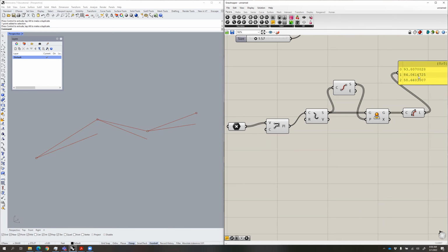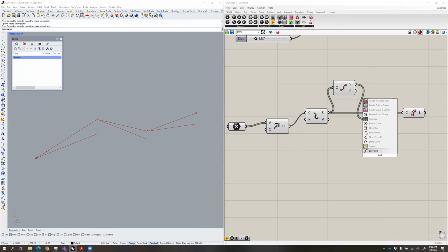Whereas over run, we got the run, we got it. Now we need the rise. So how do we get the rise? Well, the rise is simply taking the other point, right? And connecting a line from that other point to the endpoint of the projected curve, right? So endpoints, right? We're going to take this endpoints tool here and connect it to that projected curve right there. So now we got the endpoints of the projected curve.